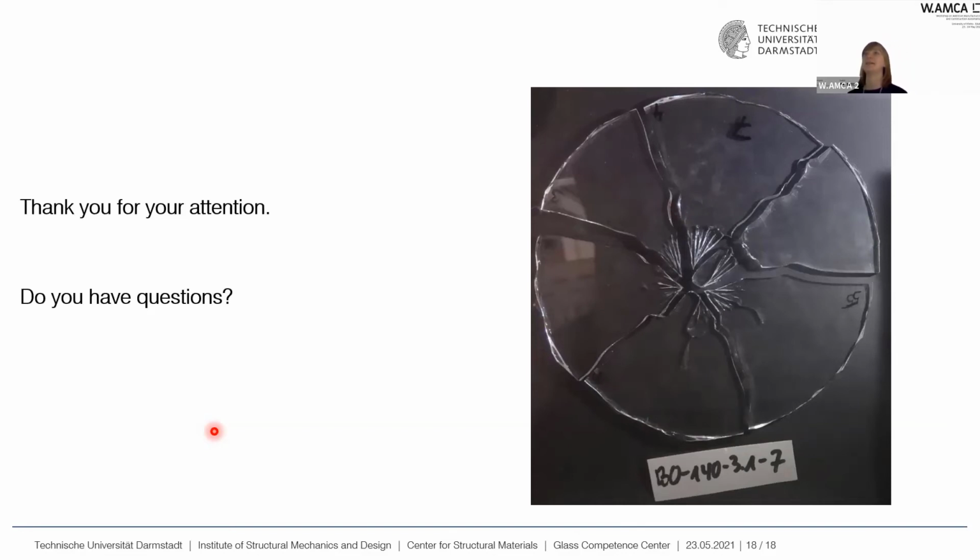So that would mean we have a stress field, thermally induced, which is not strong enough to drive cracks below a certain minimum size, right? If you have a copy of the stress field, you could get an idea of how short cracks need to be so they don't grow in this stress field.